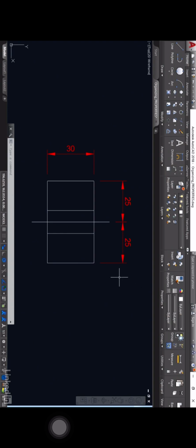Now it may be that these objects here, you'll notice, are all on layer 0. They all look the same, but they represent different things. What I could do is put them all on different layers, with different colors and different line types. But I can also do it individually by property that is loaded into this particular drawing. So this line here is on layer 0 and it's our center line.